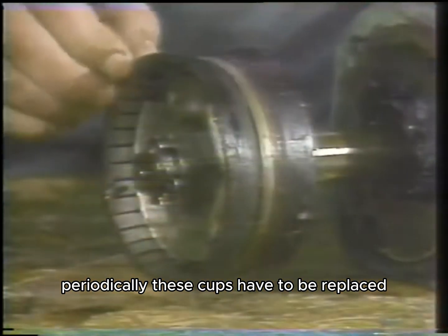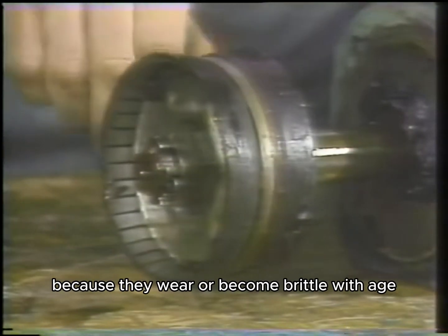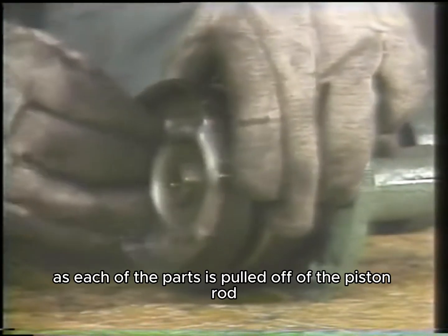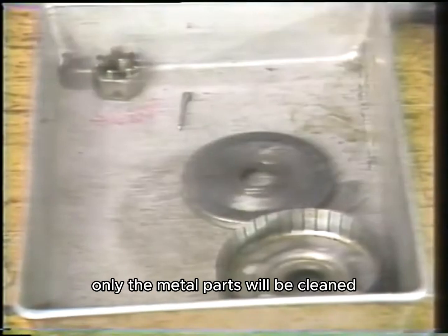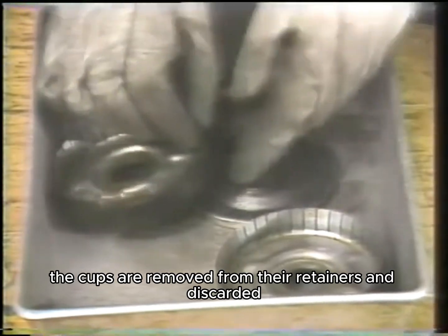Periodically, these cups have to be replaced because they wear or become brittle with age. To remove the cups, the entire piston is disassembled as each of the parts is pulled off of the piston rod. It's placed in a tray for cleaning. Only the metal parts will be cleaned. The cups are removed from their retainers and discarded.